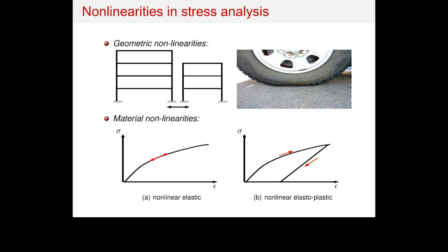I'm going to refer back to some elements we discussed in the finite element A, and I'm going to show you how these elements may become nonlinear. Now, what I'm going to discuss today is the Newton-Raphson method, basically. And this Newton-Raphson method is the most popular method to solve nonlinear finite element problems.